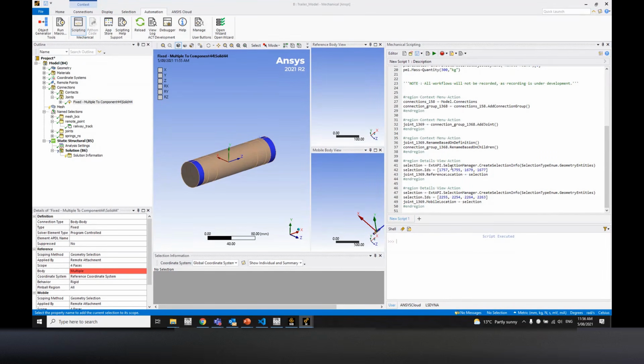And what you're doing is then just setting the faces of the reference and the scope body. So in this case, because you're recording it, only the IDs come up, but you can automate this using name selections as well, which is what I've done.